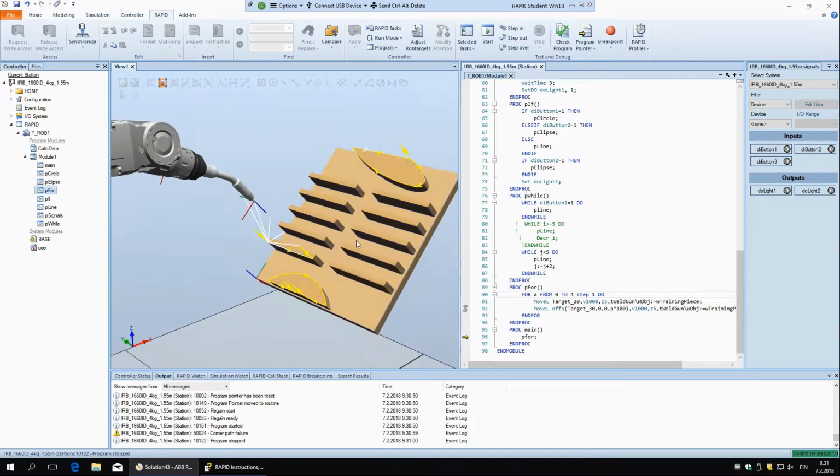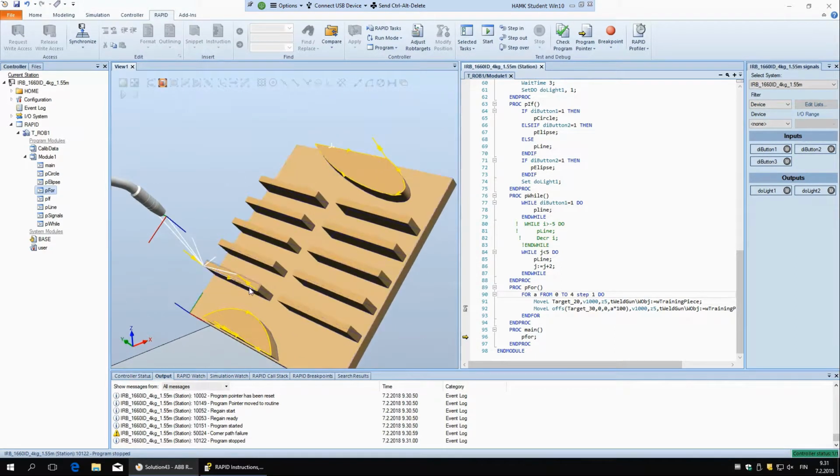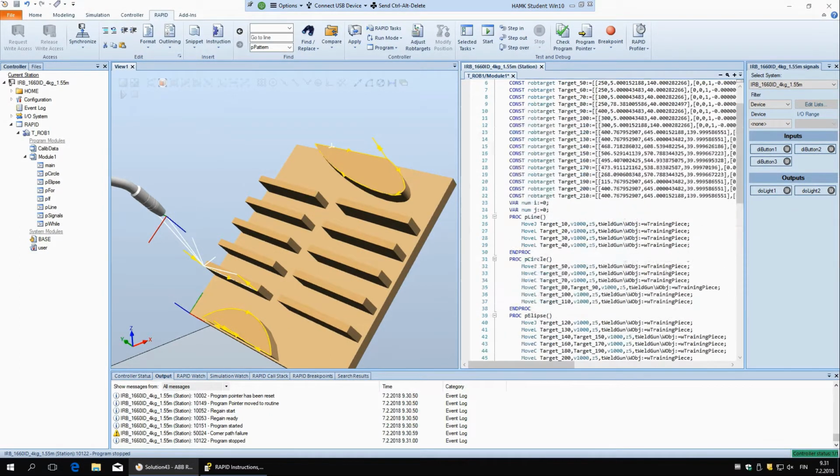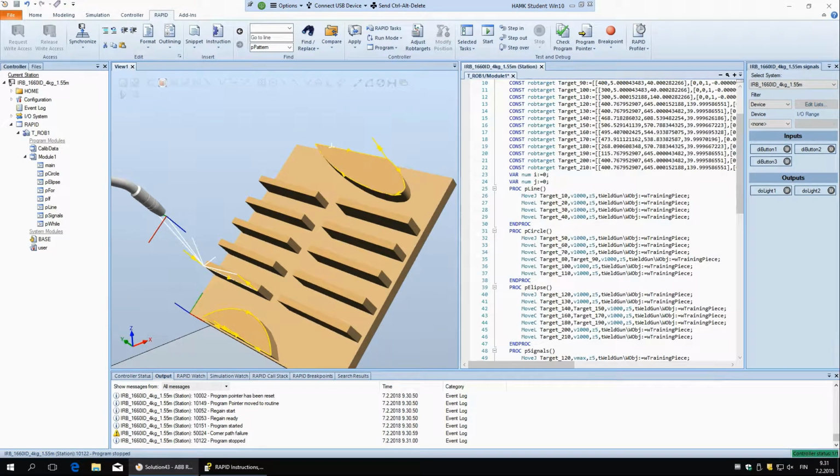And now we're going to use that to make this robot weld on all of these edges here, for example. And let's make a new process for that. Process, and let's call it pattern. And let's now copy all of these.